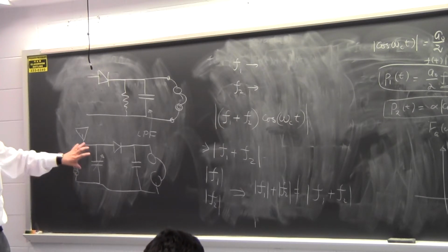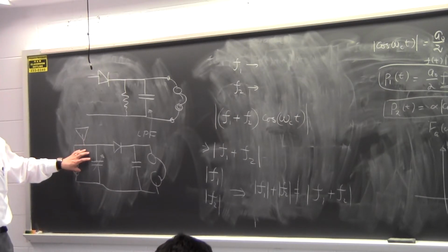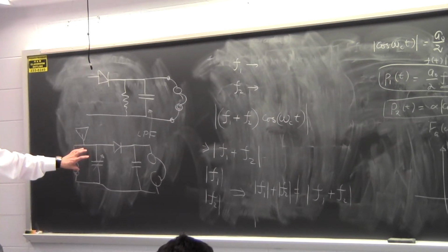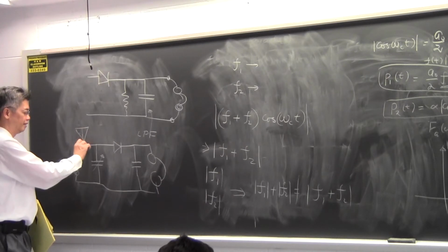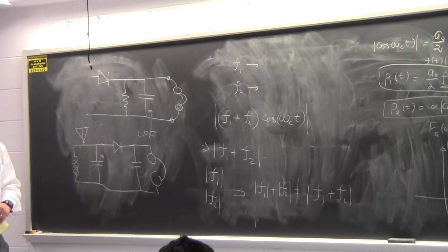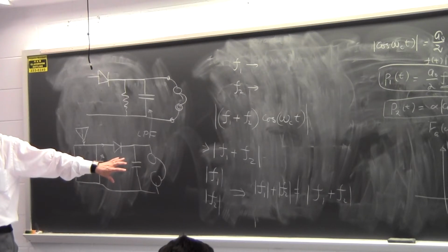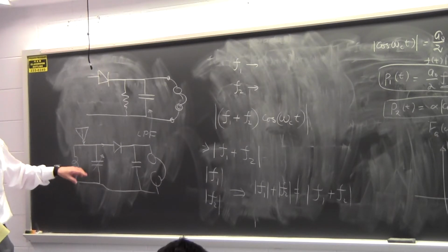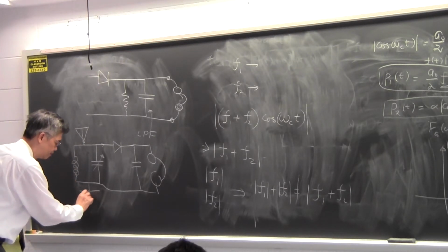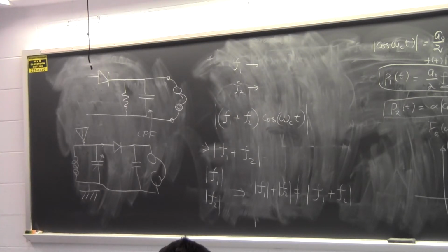580 kilohertz. What happens to this tank circuit when it's resonant? What does a parallel LC tank circuit become when it's resonant? It becomes an open circuit. So the current that comes from your antenna has no way to go back in this direction, and it goes into your earphone. But if it's off resonance, then the signal just goes through the LC tank circuit, gets short circuited and goes to ground. Okay? So this is a very simple radio that you can design.